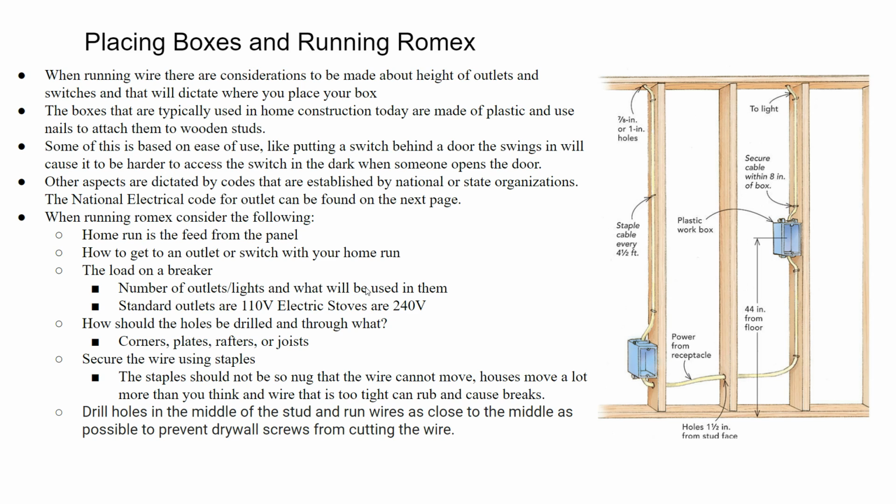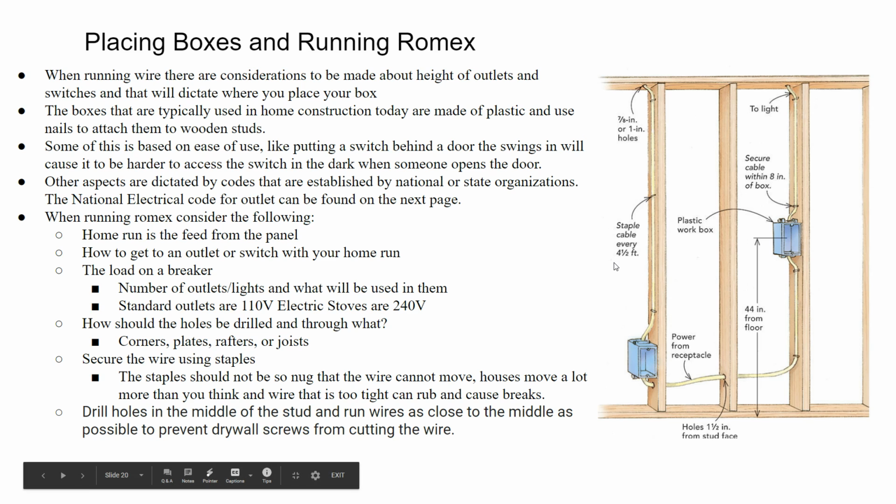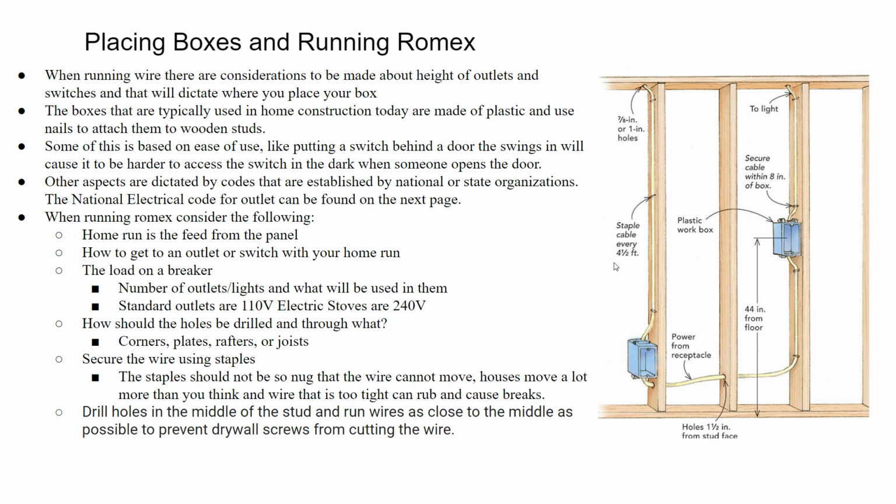You're cutting holes at certain intervals so that you don't end up with wire just running willy-nilly through everything. Because if you do that, that's a good way for someone who goes to put a screw in to hang a picture to end up running into that. That's not a good thing. So you'll secure the box.